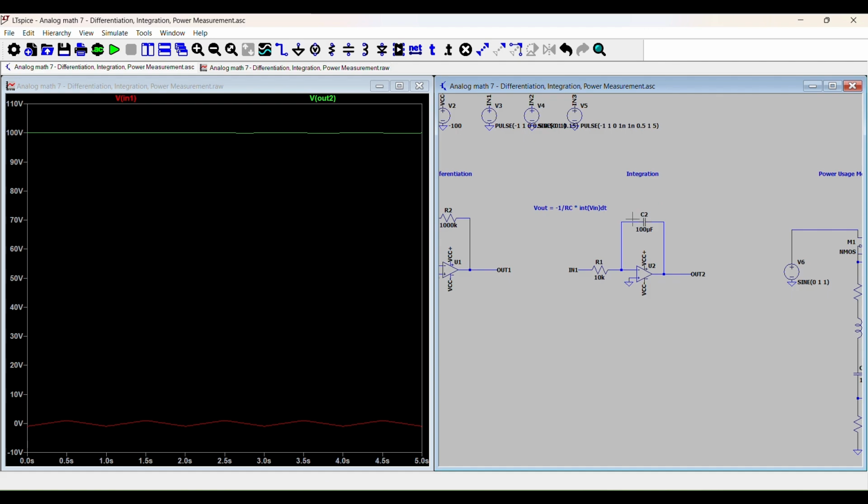So again, this is another LT-Spice quirk: they try to simulate the circuit at t equals 0 by replacing capacitors with an open circuit, because they assume that at steady state the capacitor is an open circuit whenever there's a DC voltage being fed in. If you didn't have a DC voltage, then the replacement doesn't affect the circuit at all because the voltage is 0, and then at t equals 1, the capacitor comes back and everything's fine in the circuit.